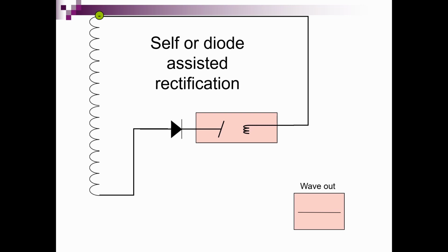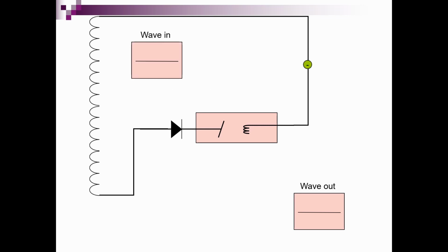When diodes became available, manufacturers added a diode to the circuit to get rid of the hot anode or excessive kV reverse conduction problems. In this circuit, a pulse of electrons arising from the upper leg of the transformer moves through the circuit unimpeded. The reverse pulse is blocked by the anode, which doesn't have a cloud of free electrons, plus the diode is blocking flow as well. So the electrons can't flow in the lower leg of the circuit, and the reverse wave produces no electron flow or radiation.